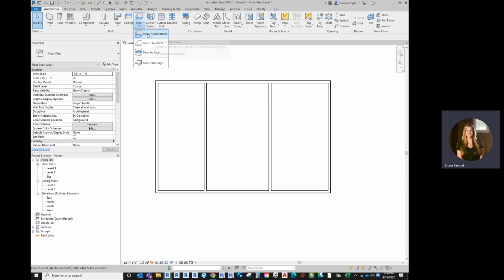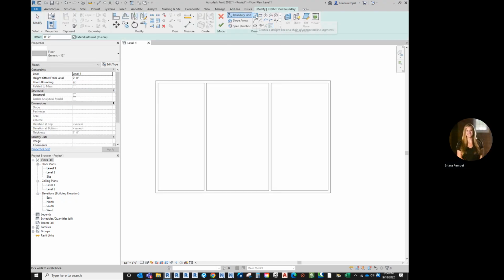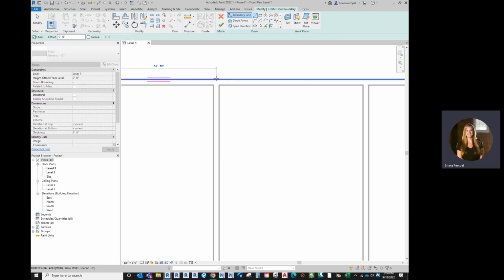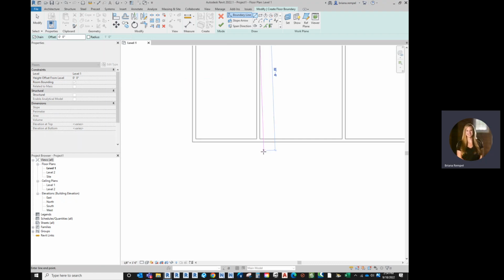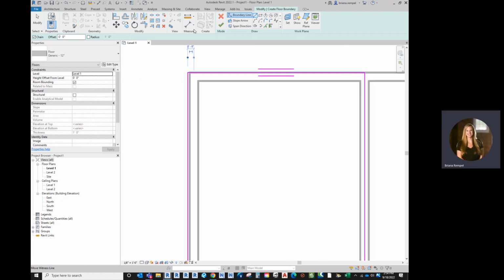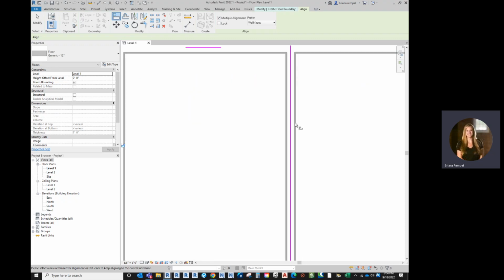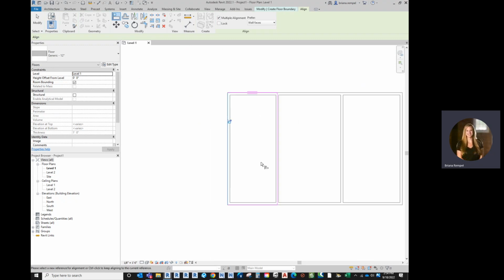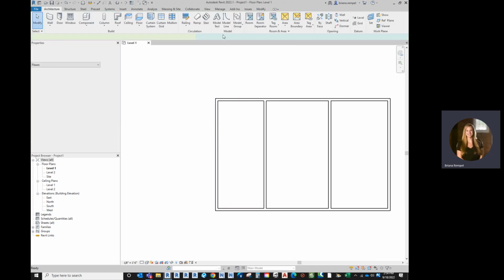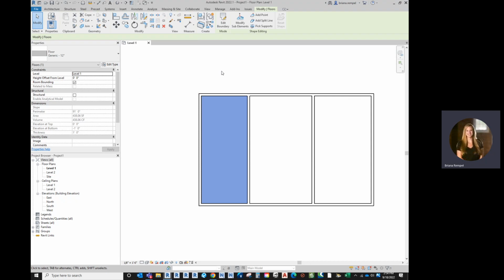So first off, I'm going to go ahead and draw my floors. I'm just going to use my sketch tool here, remembering that we're going to go to the center line of interior walls and the exterior for the exterior walls. I'm just a little bit off there, so I can quickly use my line tool to adjust. Make sure that looks like it's on the center line there. All right, so there's one floor. So I'll go ahead and hit the check mark on that one.